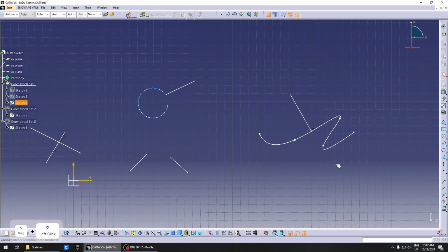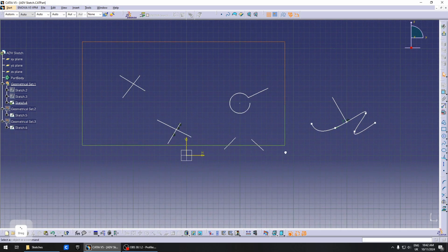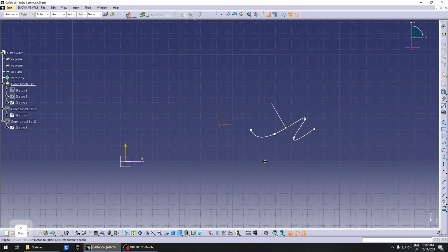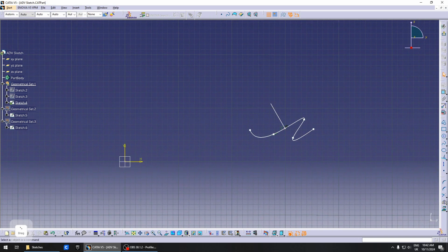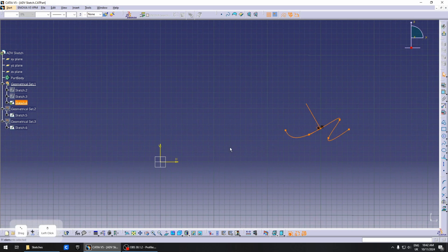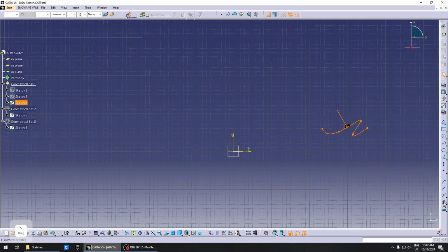All right, now let's just get rid of this. I'd like to show you some other useful stuff that you can do in the sketch. It's mostly related to the mirror and symmetries. So if you have some geometry here, you can symmetrize it to the other side directly by using the mirror and picking the mirroring plane. And it'll just create this geometry mirrored and automatically put a symmetry constraint. So when you move this, the other one moves as well. That's very useful to know. It could come in handy sometimes.